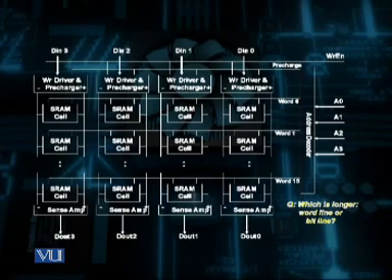The reason for this is that a typical SRAM will have thousands, if not millions of words, that is the vertical lines, and usually be less than tens of bits in length. Therefore, the bit lines are longer than the word lines.